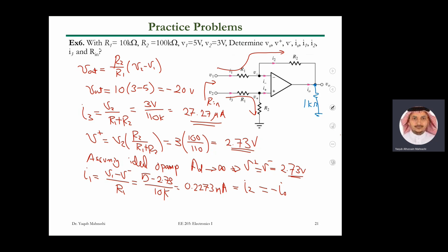Then you can find the current, whether it is flowing into the op-amp or out of the op-amp, just by applying KCL, right? Now, that current is coming from where? I0. From the supply. Look, Shabab, at the beginning the current came approximately from V1. But if you have a load, then there is another current. It should be supplied or drawn from the load. This one cannot give you that much current. So then the op-amp will supply some current, either taking or supplying the current through the load. Over.